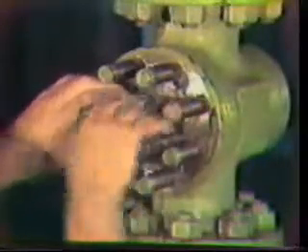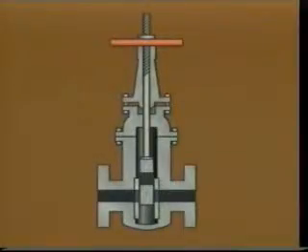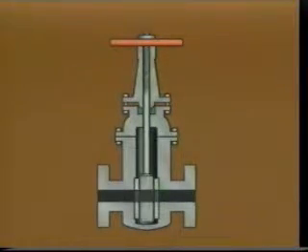The gate valves used in flow line design are basically the same as those used in wellheads. The internal components and operation are similar, with the basic difference being in the working temperature and pressure requirements. As in wellhead use, the flow line gate valve should never be used to throttle the flow rate and should be operated either in a fully opened or closed position.